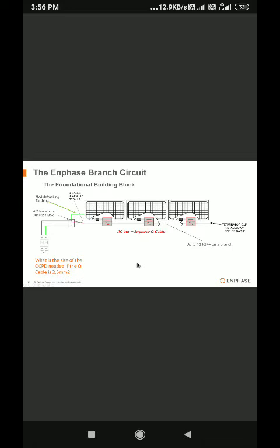Right? So as the inverter generates current, it is contributed onto the cable down the wire, and the current is backfed into the circuit breaker or in the service panel. So one of the primary design parameters of Enphase system is the simple understanding of how to calculate the maximum number of microinverters that can be accommodated on a single branch circuit. So if I consider this as one branch circuit, how to calculate how many microinverters can be there.